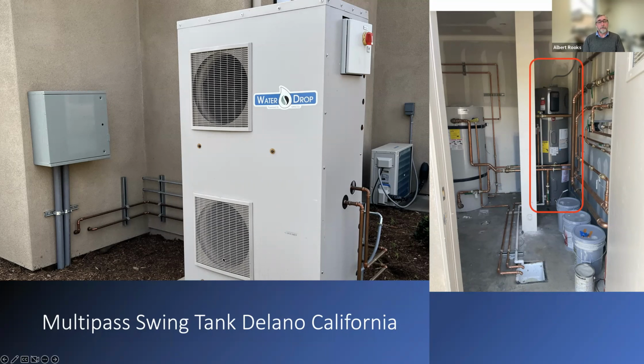But essentially this is the same story as those earlier slides. Heat pump there on the left. That little middle picture is a 119-gallon tank, so that's primary storage, and that's full of 150-degree water. And the little red circle is a Rheem 80-gallon heat pump water heater. It can be operated in hybrid mode, or in heat pump only mode.